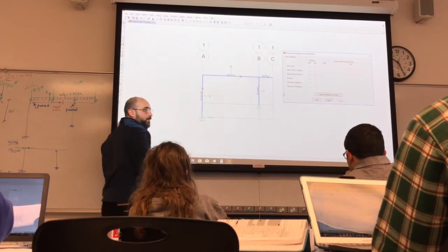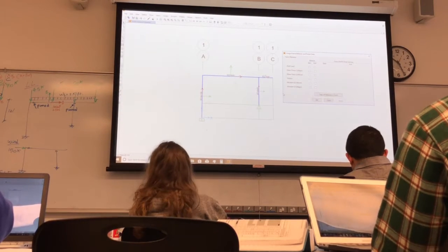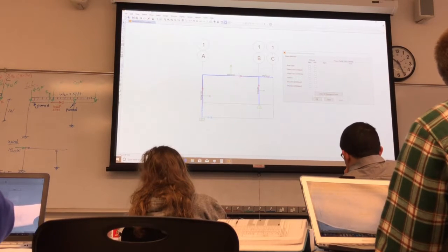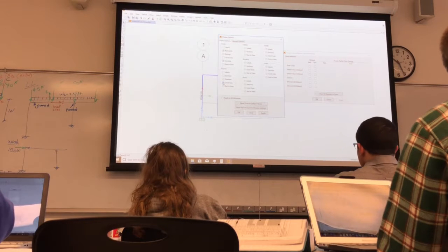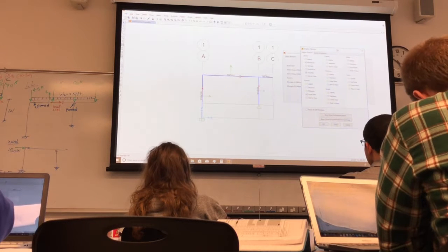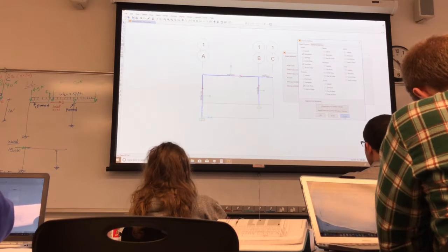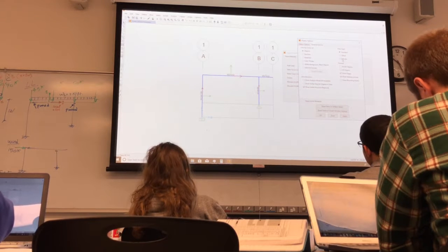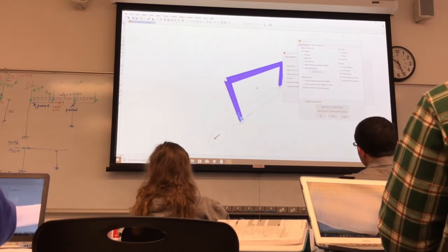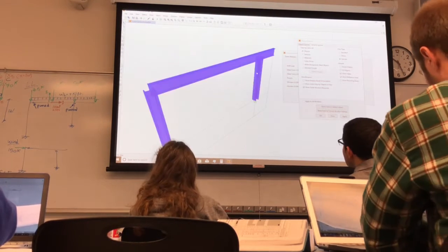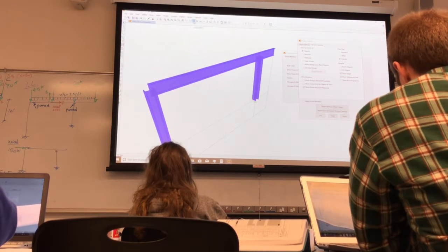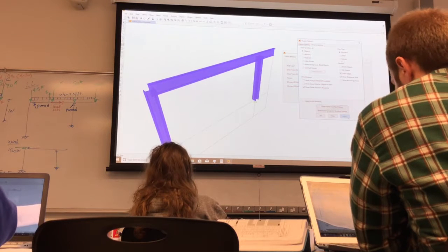Can you show us how you put those all together? The arrows, yeah. Go here, you see this display thing, and then you click here, local axes at the frames, and click apply, and that's how it shows you. Yeah. And it gives you many other options, but you can show something called extrude. If you look at 3D, you see the beams, you make sure the beams and columns are put right, you see the I-shaped beams, how they look like. Many other options you can do. But anyways, we're not doing extrude.